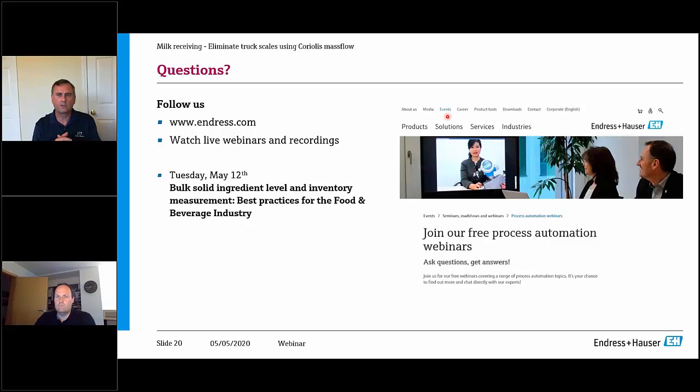I would say it's not going to be, again, caveat to that: if you have really little or no air bubbles in there, then the milk fat accuracy is going to be quite good. But as soon as you have some micro bubbles in there, that will start affecting the accuracy of the milk fat. So that makes it very difficult to put an accuracy statement or an accuracy number to that, because those micro bubbles could affect the accuracy of the density measurement.